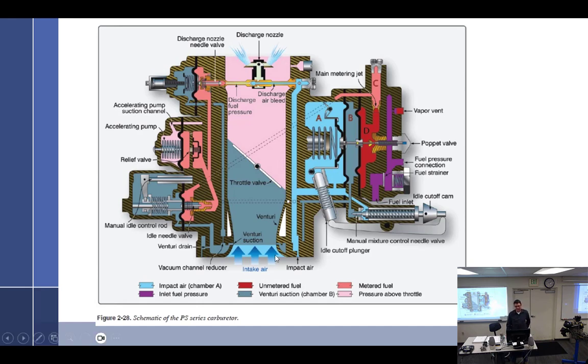And then this would open that up more, is my assumption. But it is possible, with the engine off, to put the mixture in, which releases the spring and opens up the poppet valve, turn on the electric boost pump, and fuel is just going to come up and run through here, over to here, around through here, up, open that up, and start spraying out of here, or running out of here. And if it's updraft like this, and the engine's not turning, the fuel will come down here and start puddling up down in the air system.